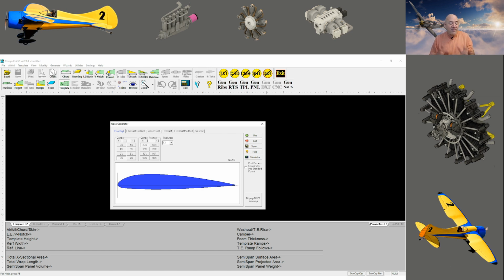for a model aircraft. Keep in mind, with a model aircraft, the smaller you get it, the fewer molecules are touching the wing surfaces. Okay, that's the reason we went to cube wing loading. Some people get mad and say, well, it doesn't work on full scale. Cube wing loading was never invented for full scale. It was invented as a way for model aircraft to know how your smaller airplane is going to handle versus a larger model airplane, and how the weights matter with the way the plane's going to perform.